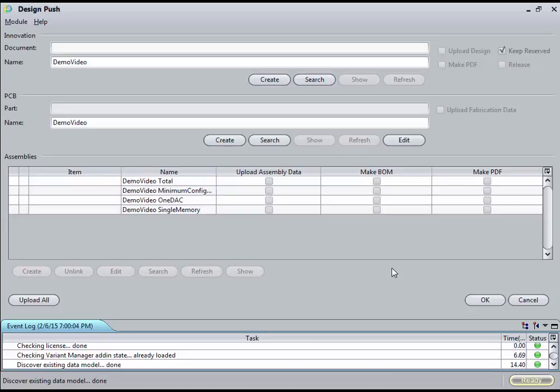Three important areas should be mentioned in this module. The first one contains functionalities around the project itself, including the design container, the assembly variant independent schematic drawing and the release aspects. In the next part, the PCB is handled, including its fabrication data. Finally, we see an area which handles all variant-specific data, including variant-specific schematic drawings, pick-and-place files, and bill of materials.